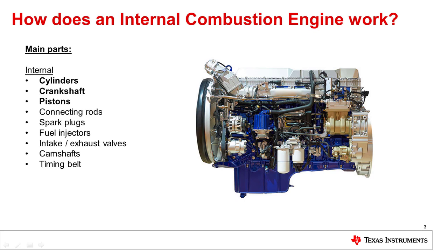An internal combustion engine, known as an ICE, is a heat engine in which the combustion of fuel generates force to do work. At the heart of the engine are the crankshaft, cylinders, and pistons, which fire off in a pattern to convert linear motion into rotary motion of the crankshaft. Many other components such as intake and exhaust valves, camshafts, and the timing belt are used to increase the engine efficiency. All of these parts are structured inside the engine block and cylinder head.